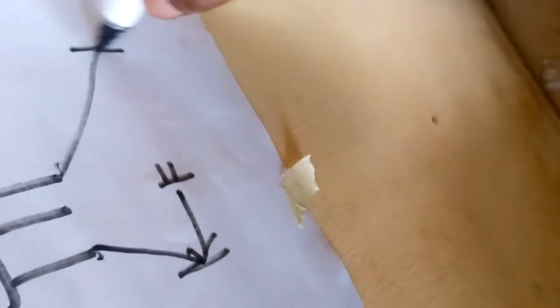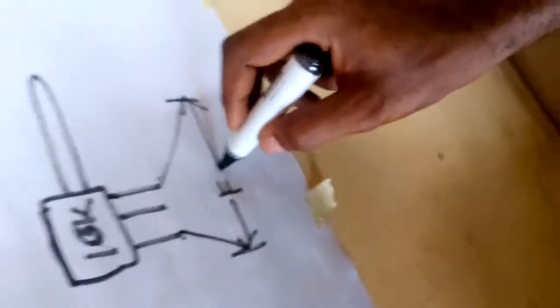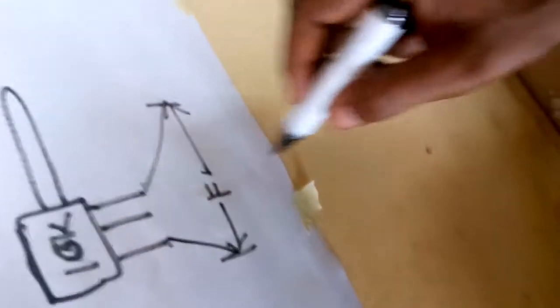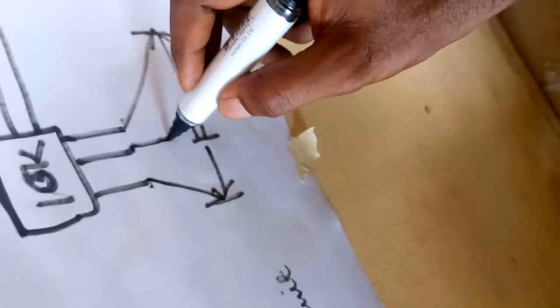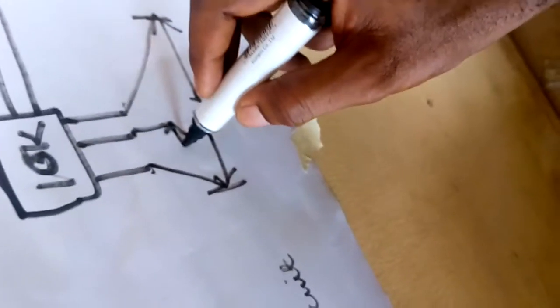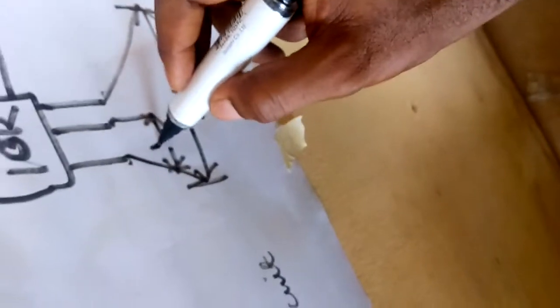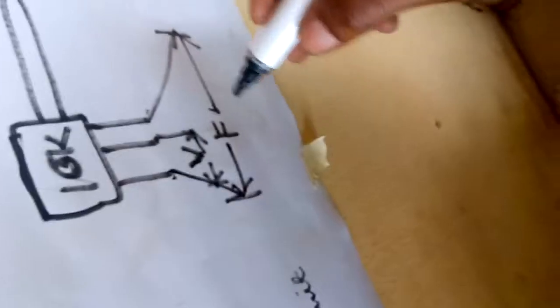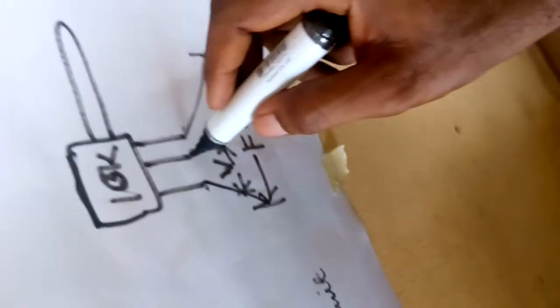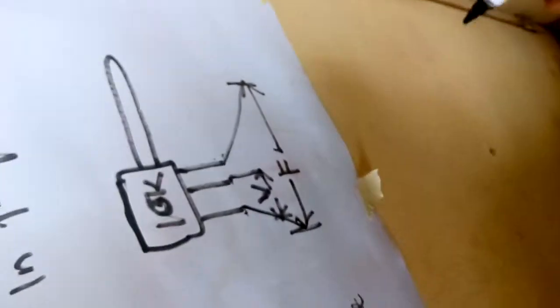If you read it with your meter, it will give you a fixed resistance. But if you make use of the middle one and any other one, it will be varying. It will give you a variable resistor. So that is how you use it. You can actually use these two or these two for variable purpose. So that is how you do that.